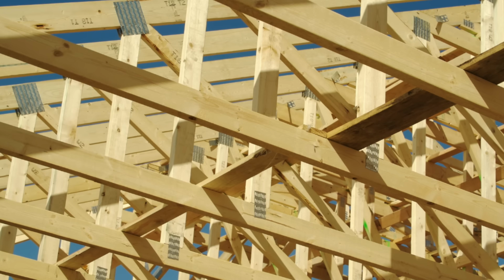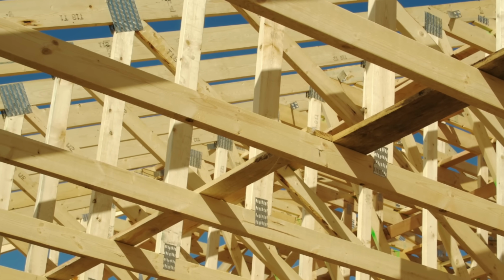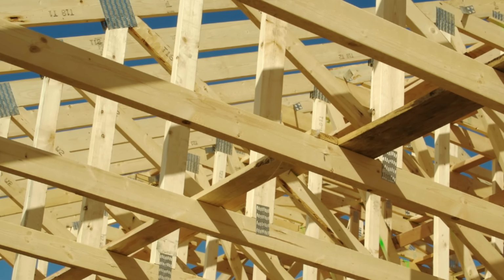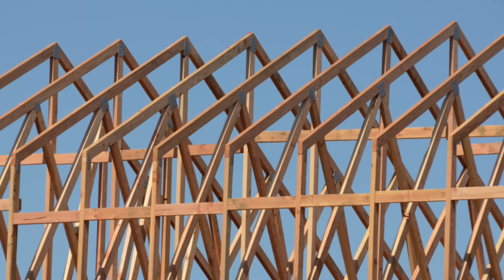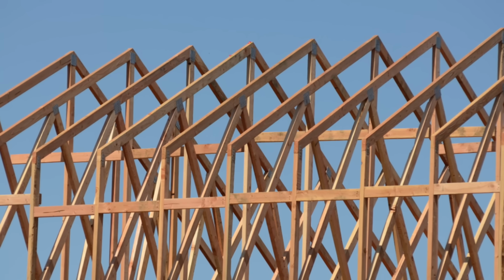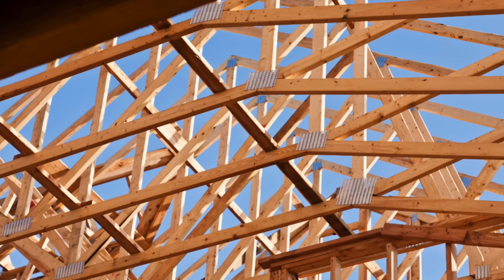Now that's a traditional roof, but many newer homes and smaller commercial buildings aren't necessarily built this way anymore. Instead, they're built with something called roof trusses. A roof truss is an engineered, pre-assembled unit that creates the shape and structure of a roof. In truss roofs, multiple trusses are installed side by side, like rafters, and braced together until the roof sheathing can go on. Trusses are really kind of miraculous.